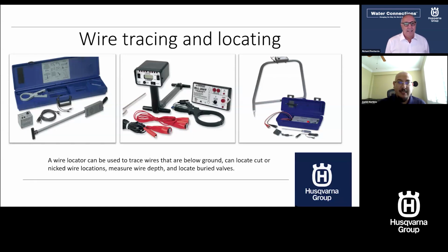What I do highly recommend is using a quality wire tracer. My go-to is the one in the middle there. It's a buried line locator made by Greenlee Tempo. The one on the left is kind of your industry standard 570 or 720 detector. It takes a little bit longer. I highly recommend going with a better tool for this type of job. On the left, it looks like I could maybe find some coins or a ring with it. Yeah, absolutely.